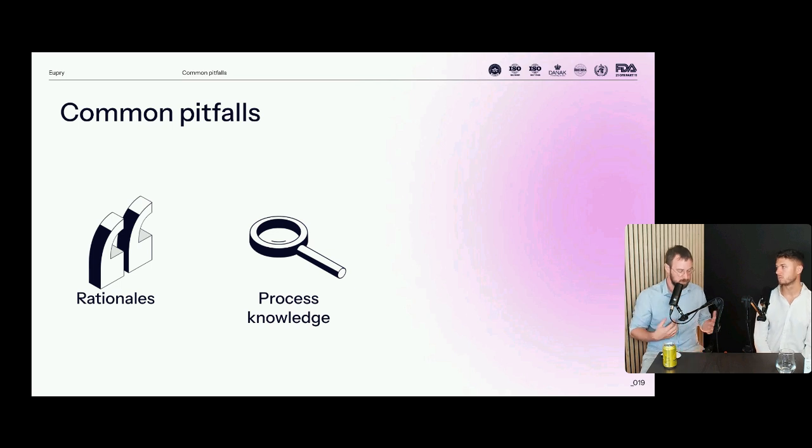So if I understand you correctly, the question is basically if you perform a mapping during winter and one during summer, and those have different hot and cold spots, do you then switch around the sensors? That's also one of the questions we get a lot. Do you switch the position of the constant monitoring system? We would normally advise not to, but basically to keep a sensor in each position. And the rationale behind that is that you don't know when exactly the hotspot changes.